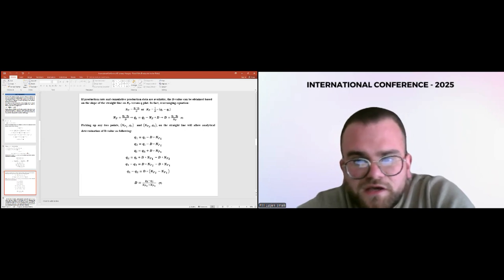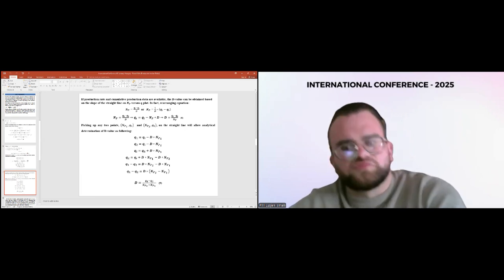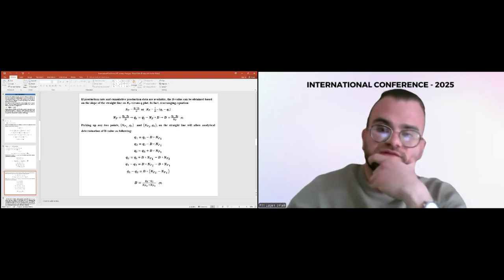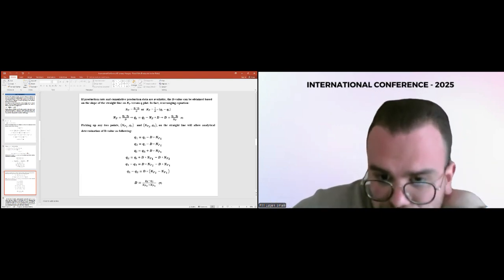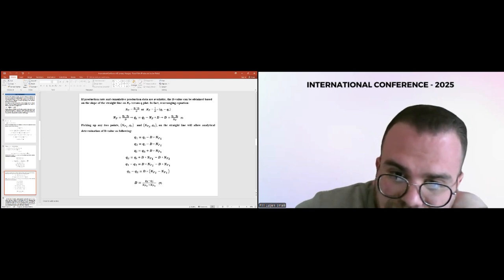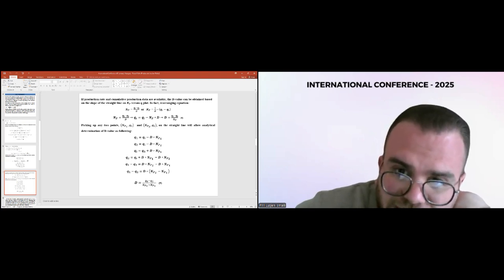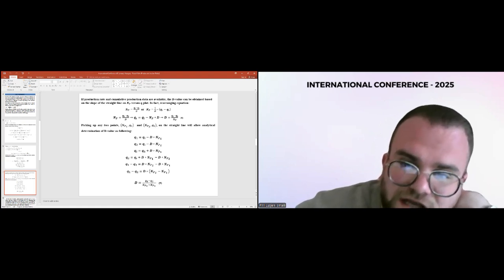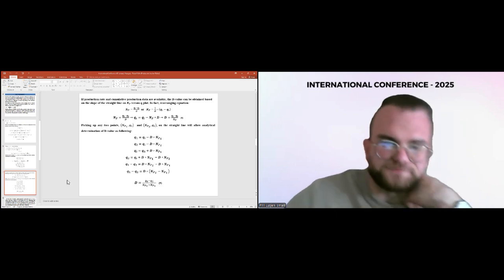In this case, based on two different calculations, we can come to conclusions 8 and 9, which is another value of decline rate for exponential decline, d equals qi minus q divided by Np. Here qi is the initial production rate, q is the rate at time t, and Np is cumulative production.